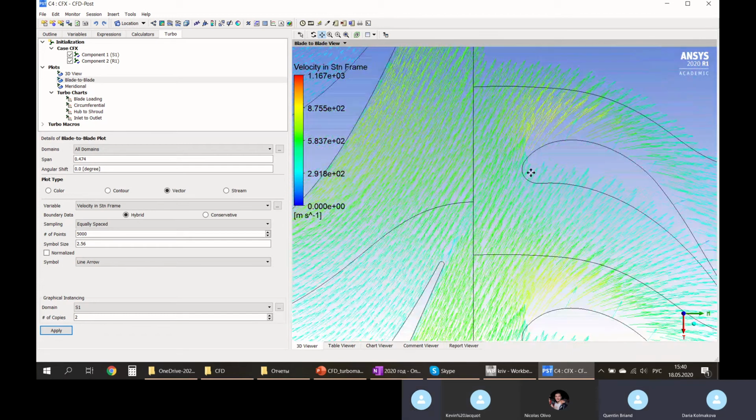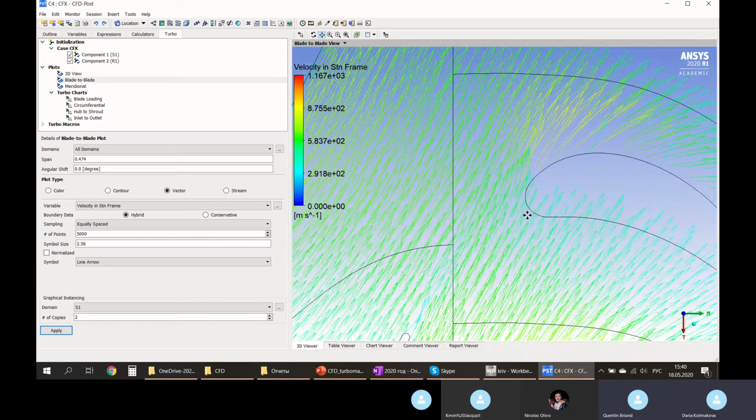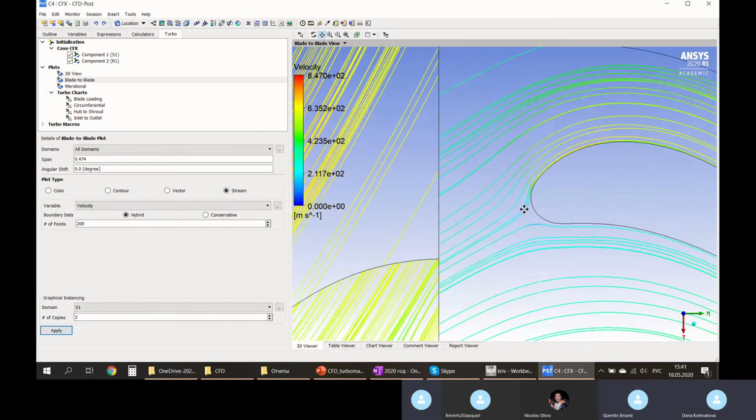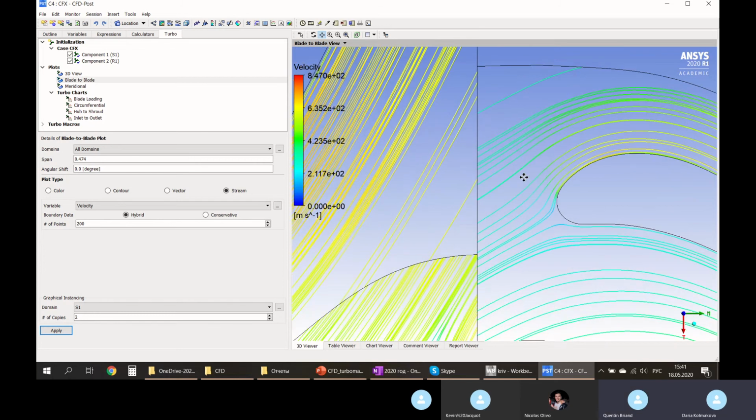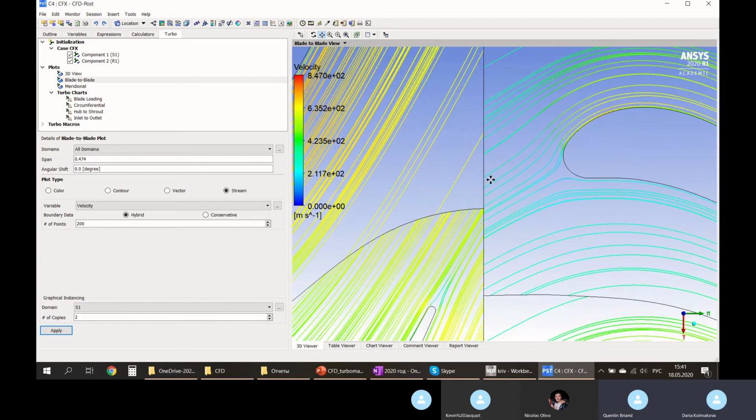Here, yeah, quite okay, but I think something can be improved. But in general, using streamlines, you can see that the streaming is going okay. So be careful with compressor blades, I mean rotor blades. Using the vector picture, you once again can say that you've selected the proper alpha 1 angle while setting up your model. Okay, I think this is the second criterion for you.